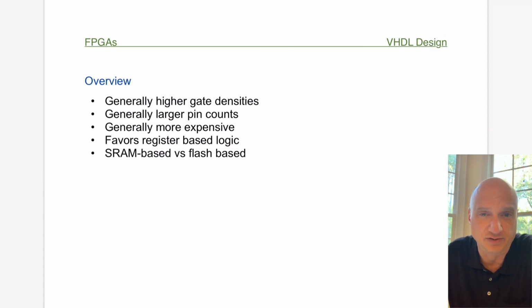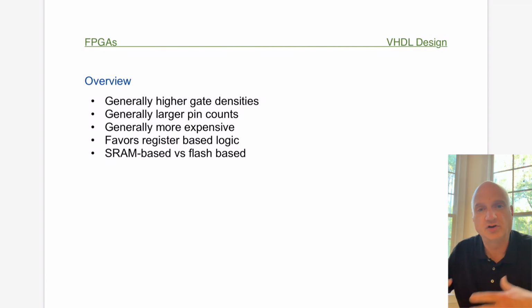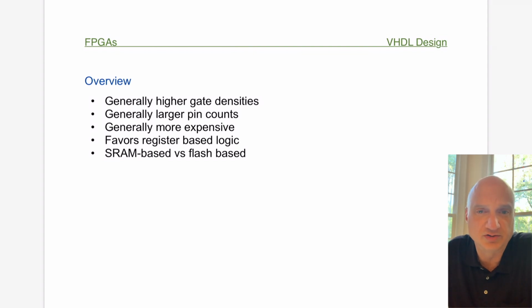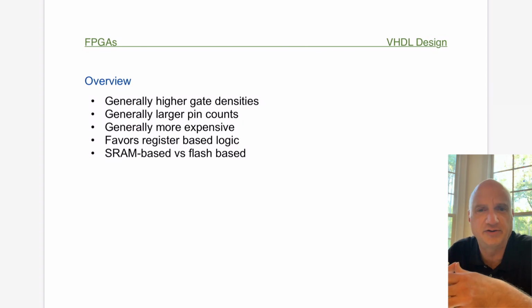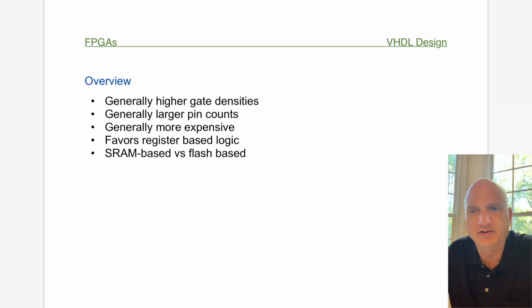There's a wide diversity of components that are FPGAs, with multiple pinout options and cell density options and a whole slew of things. That seems to be where the greatest growth is happening in programmable logic, in the FPGA arena, and we're seeing lots of different devices coming out with new features. So we're going to talk about how a basic FPGA works internally, what the structure looks like, how they handle combinational logic, and basically how they function inside. And we're going to do some examples of implementing some designs using VHDL hardware.